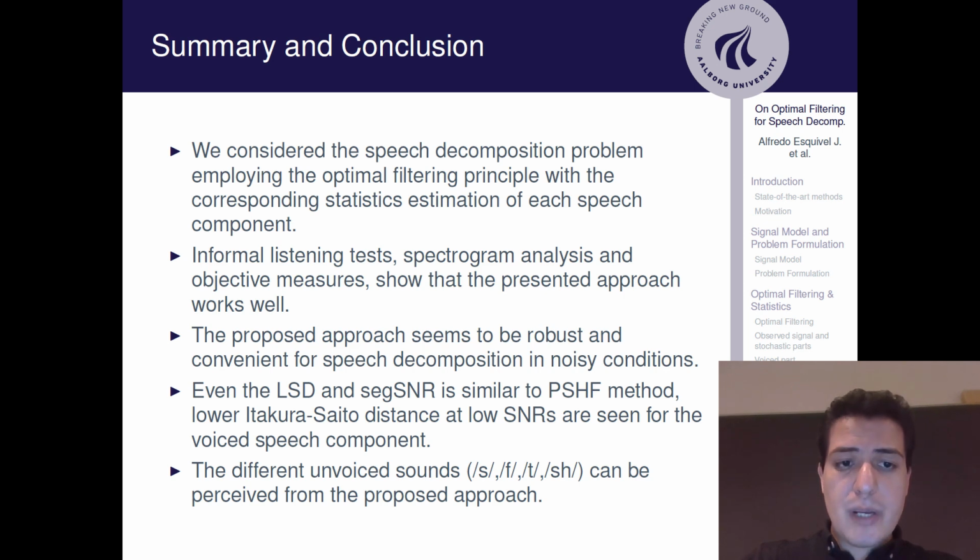Even if the log spectrum distortion and segmental SNR are similar to the pitch scale harmonic filter method for the voice speech component, we got lower Itakura-Saito distance values at low SNRs. And with the presented approach, the different unvoiced sounds such as S, F, sh can be perceived.